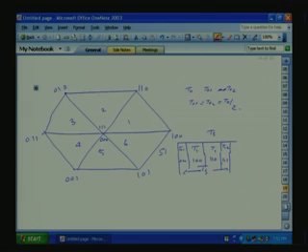These are the zero periods. In the next sampling interval, we will find T1, T2, T0 in sector 1 itself, but the previous state is 1 1 1. Then we will reverse the sequence. That means the next sampling period will start with 1 1 1, then 1 1 0, then 1 0 0, then 0 0 0.